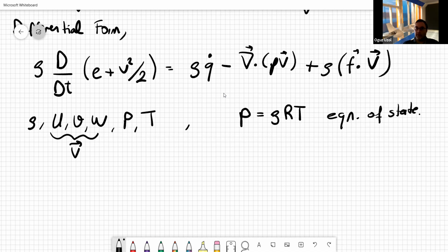So this is our sixth equation, but there's one thing that I forgot to mention. Here in the energy equation, you do not see any temperature, right? Where is temperature? There's no temperature here. There's a temperature related quantity, which is actually E, internal energy. And for a calorically perfect gas, we know that E is related to temperature: CV times T, so internal energy.